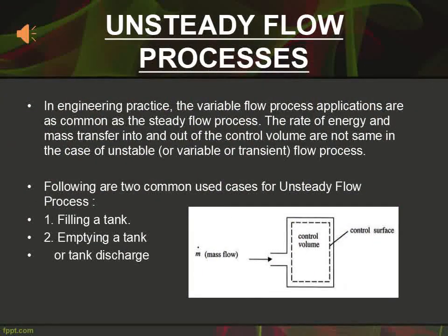Now next is unsteady flow process. There are two common use cases for unsteady flow process: number one is filling a tank, number two is emptying a tank or tank discharge. Before going to the application, I would like to explain what an unsteady process is. An unsteady process is a process in which the rate of mass or volume in a control volume is increasing or decreasing with respect to time.